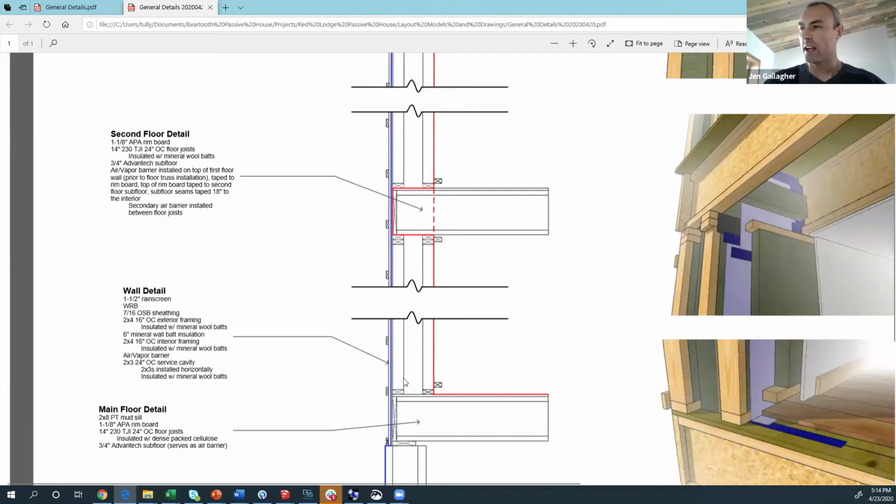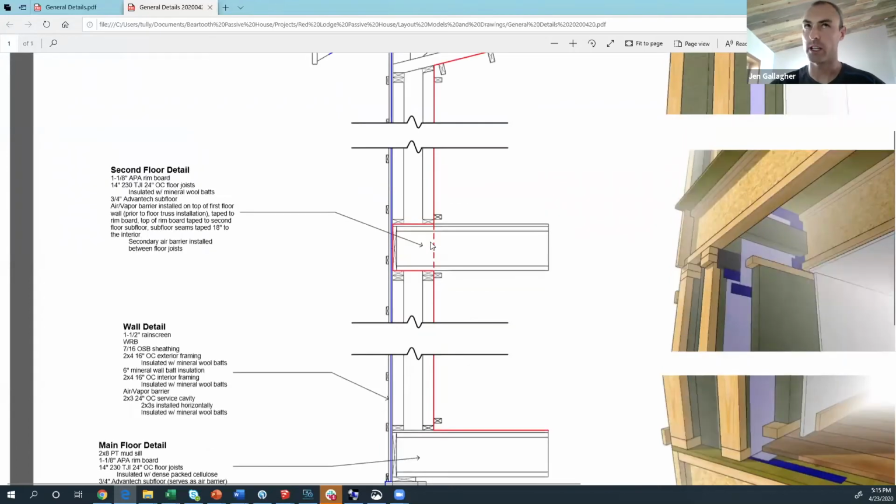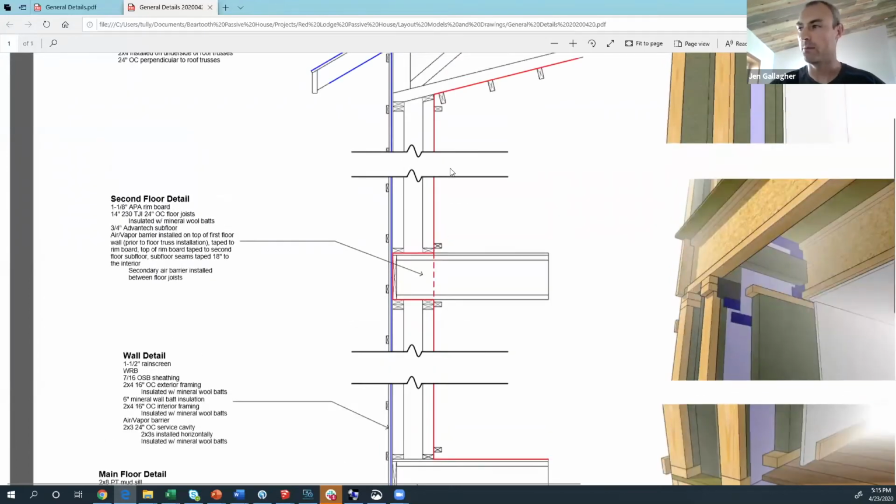I like the fact that if you were a contractor and you were wanting to put up houses relatively quick, you could do it because you get a framing crew to build you a 2x6 structural wall and do the framing for the entire house. And then maybe your more specialized crew, if you do stuff in-house, can come in and build that interior wall and do any of the additional, more intricate framing that the double stud might require.